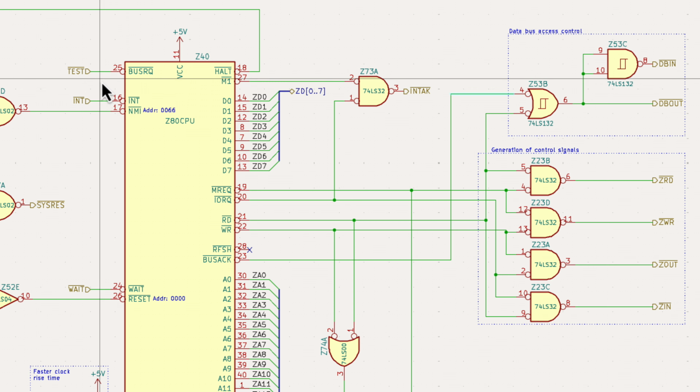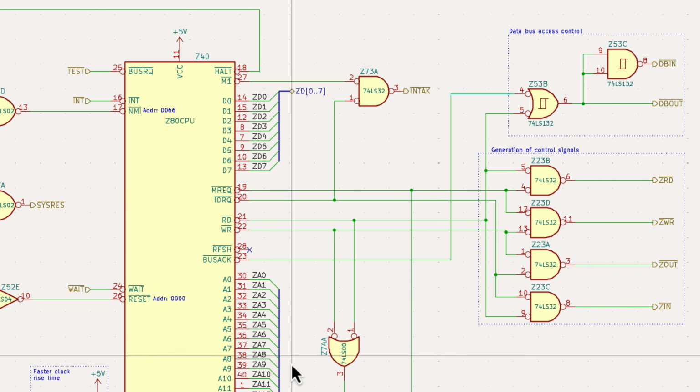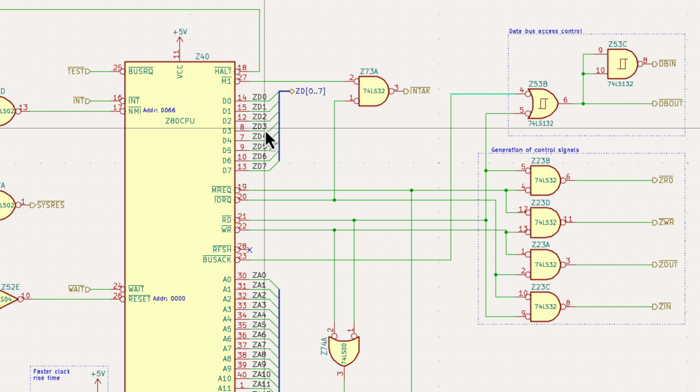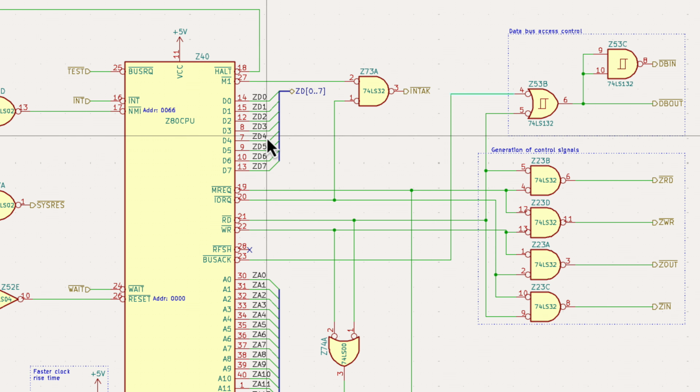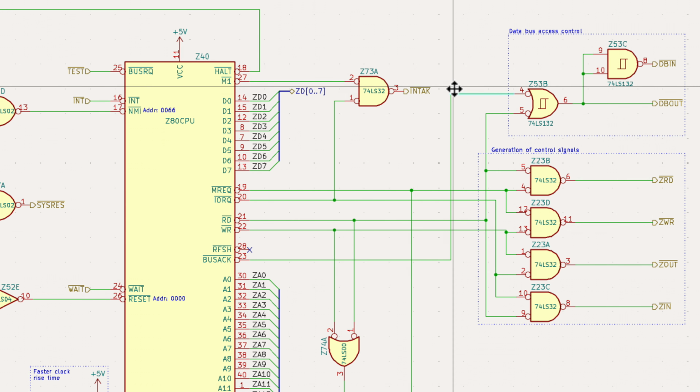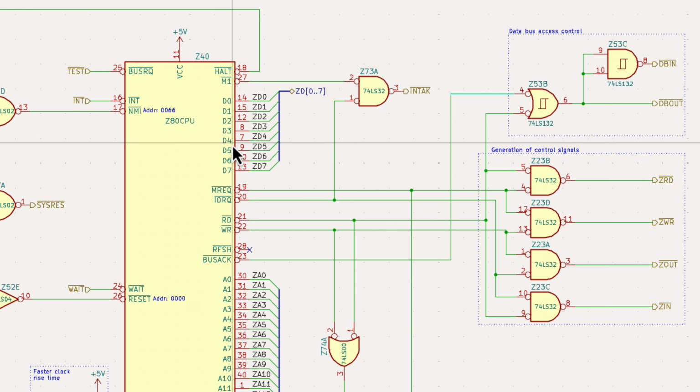What happens here is anything that's read or written to the data bus will be corrupted because it's in the middle of the execution, and there's some likelihood that there's something going on the data bus, reading or writing. Either of these could corrupt the current state of the CPU and crash it. If we let it go first and then only disconnect it afterwards when the CPU is ready, nothing of this will happen.